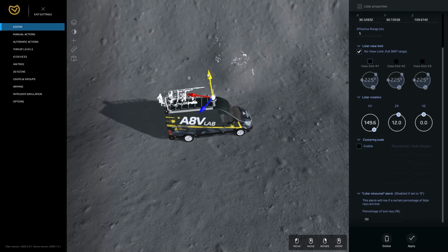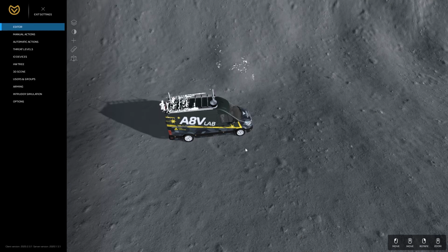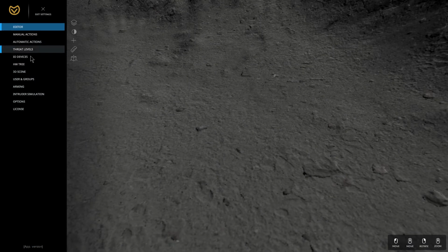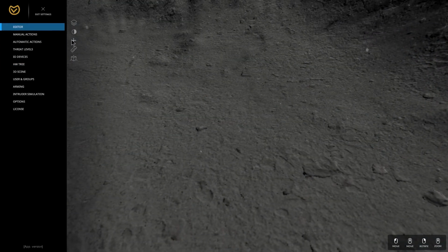I would then take the number of 10 minimum points count and divide it by 2. This means that at 20 meters, I will need a minimum of 5 points clustered together to make a bounding box that will activate the alarm inside the zone. But don't worry about this. It will get easier and easier with time, though, don't worry.